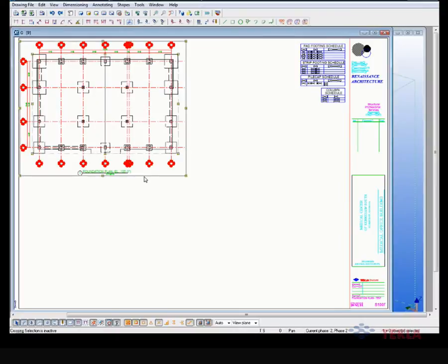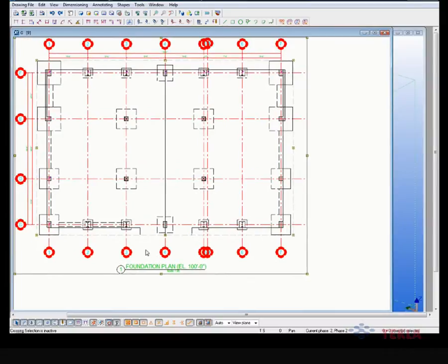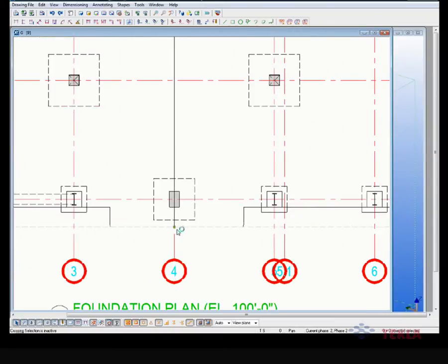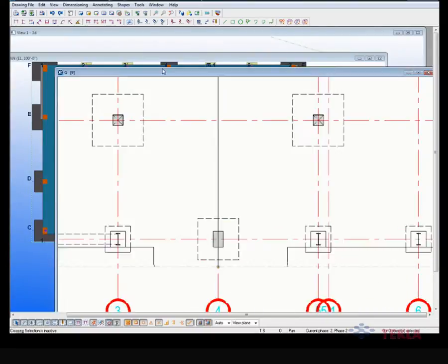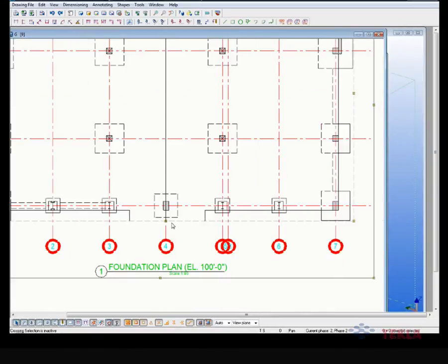This view has not been modified since I put it in there. And we can see with the properties, we can see the view Extrema going around. So notice how the view Extrema is cutting off the slab, because that's matching exactly what I created from the model. So this link between the model and the drawing views is an initial link.